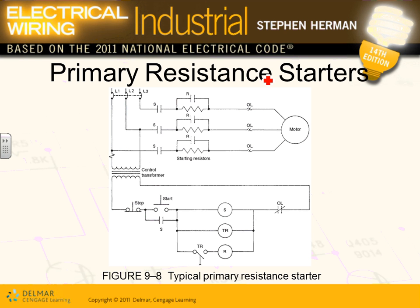The second thing that we would like to talk about, guys, is primary resistor starting. If you have a 50 horsepower motor and you start the 50 horsepower like this, you grab that and you turn it on, you know what's going to happen? It's going to suck so much energy because of the inrush, and the light in your building will dim.